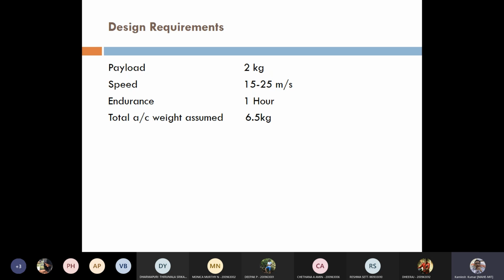Based on that, your wing size will be around 1.5 meter or maybe 2 meter itself. If less than 2 meter, it will be tough. Maybe 1.2 meter approximately can support 3 to 4 kg, with not more than 300 to 400 gram payload. So you have to check what maximum wing sizing can be there.